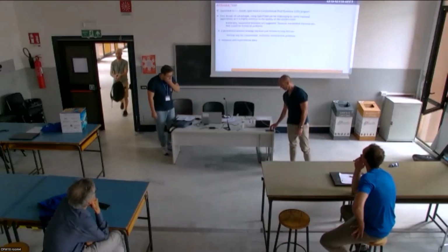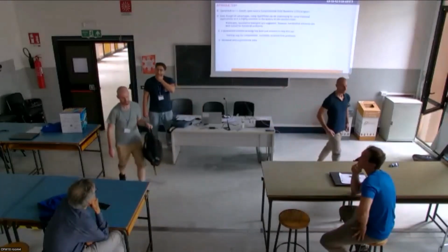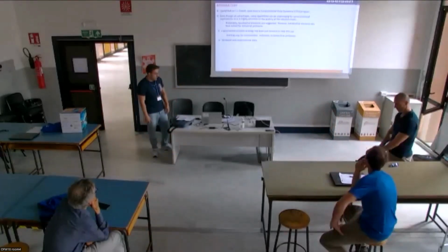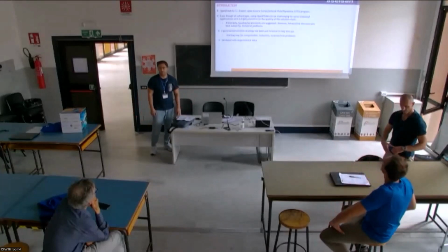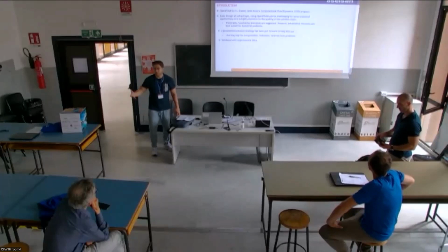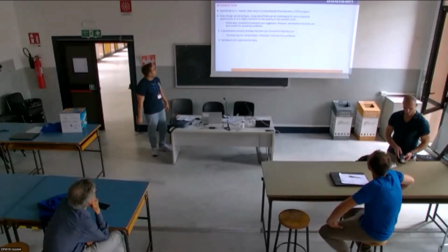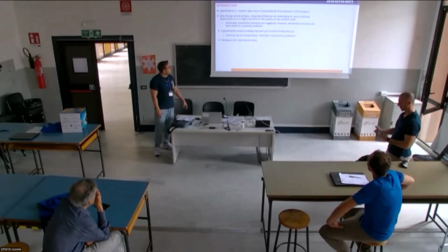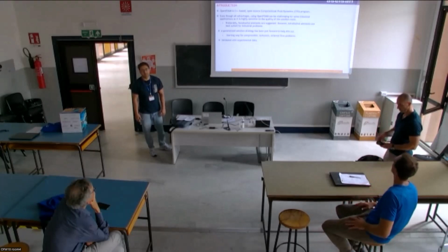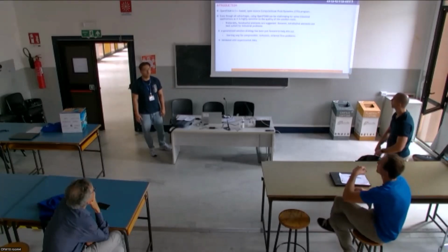So as an introduction, as we all know very well, OpenFOAM is a CFD tool, C++ based, and it's free, it's open source, and it has rich documentation, and everyone can do every manipulation on the code. But even with all the advantages, using OpenFOAM can be challenging for some industrial applications, which are highly sensitive. The reason is that OpenFOAM shows high sensitivity to mesh quality.